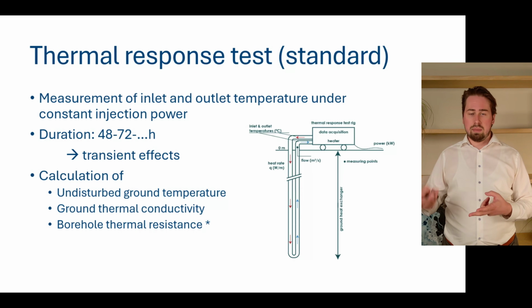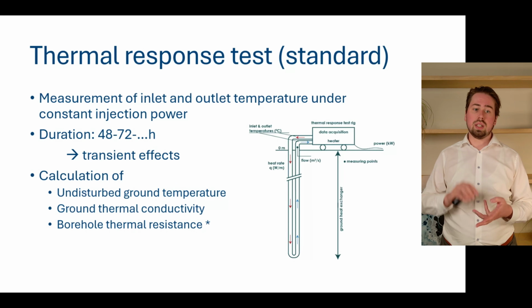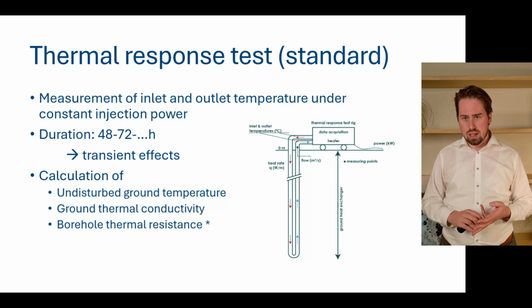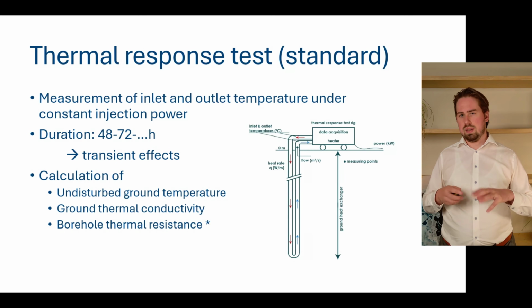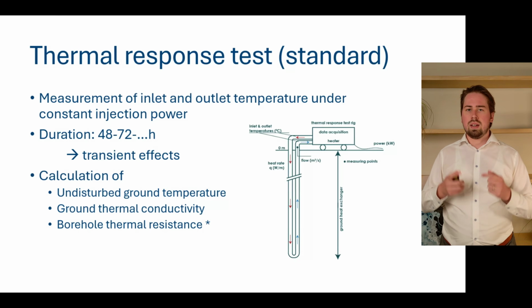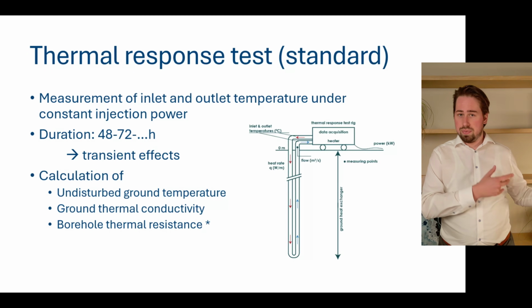You can mathematically, as we will discuss in a second, extract the ground thermal conductivity as well as the borehole thermal resistance. Now, this borehole thermal resistance, I placed a star next to it because yes, you can get this mathematically, but it's not always a good idea to use this value directly for your design.